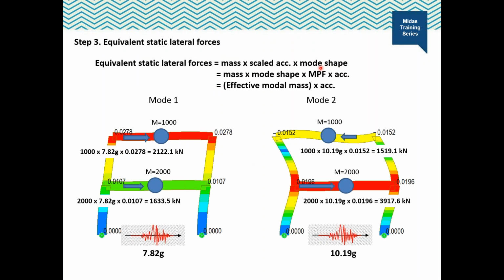For each floor, mass times mode shape times modal participation factor gives effective modal mass. So, you can also calculate equivalent static lateral forces by effective modal mass times acceleration, directly read from response spectrum. Midas provides this effective modal mass.